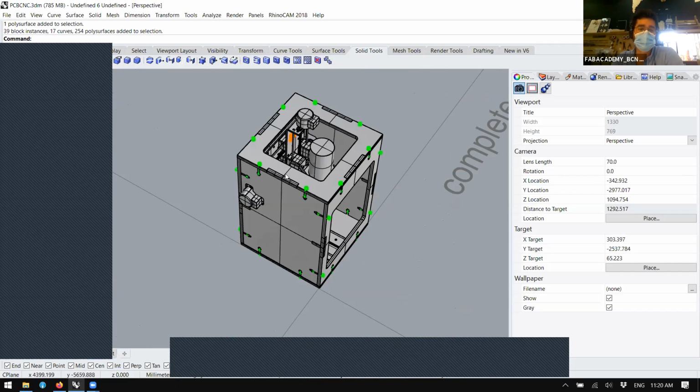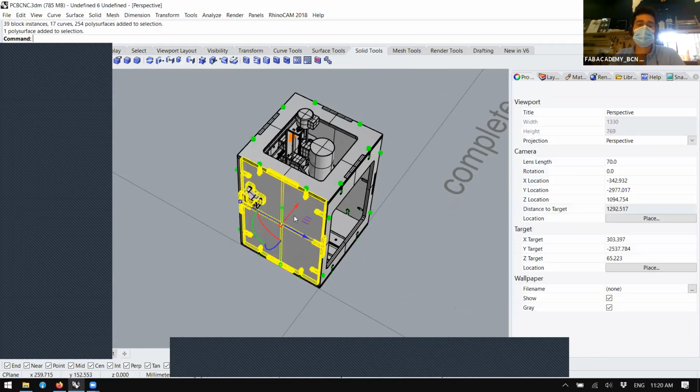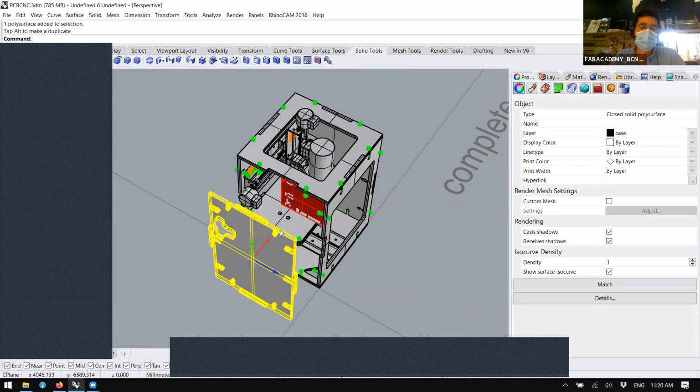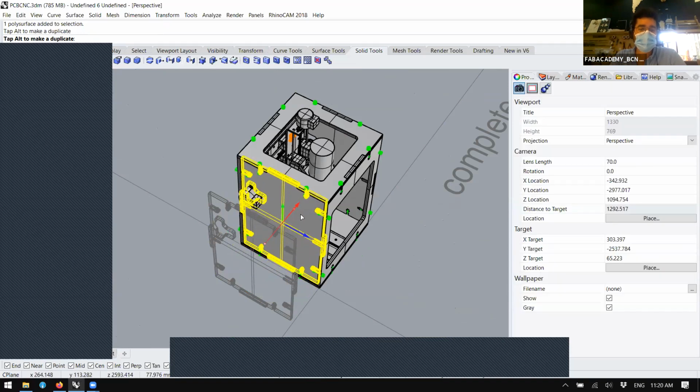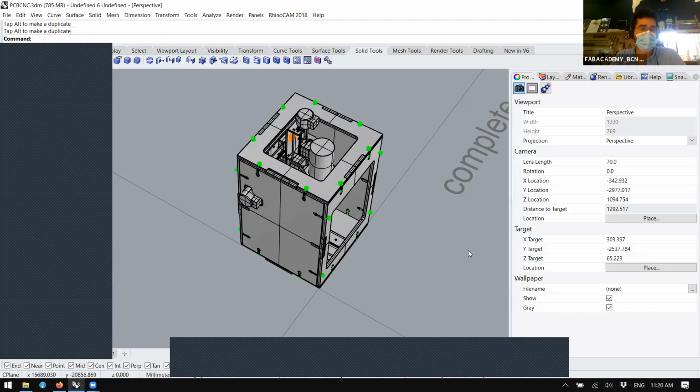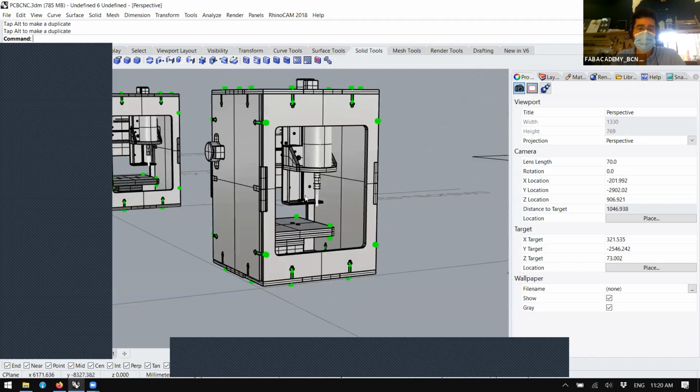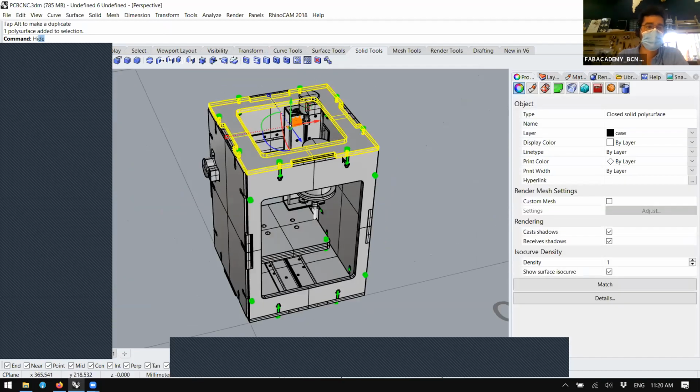When you have this one, what I always recommend is, okay, you have this machine. It's a little bit annoying, but make an assembly step by step of the components. Let's say explode it and start joining them together, but do a procedural assembly, just moving the pieces manually, so you know that you are able to match one part inside another one. And that's quite important.